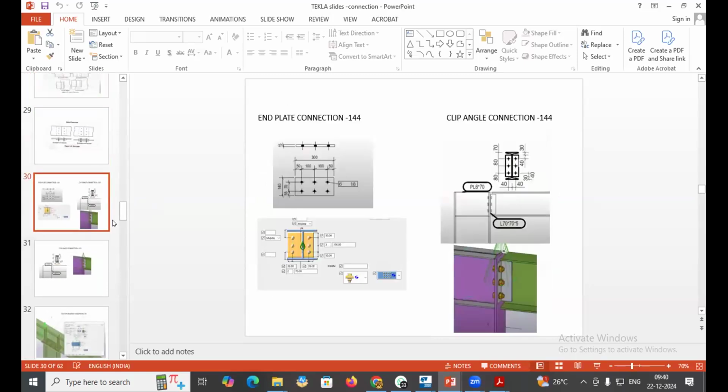And there are some sample connections here, and I have highlighted the values also here, and how we are going to work, because this is the 2D set of drawing. Based on the 2D drawing you have to work in 3D, how to create the column, beam and the connection. And the reverse process is, after finishing this connection you have to give numbering, and after giving numbering you will highlight the names which we provided while creating the beam and column. That will be highlighted after extracting the drawing from the 3D model. You will get this kind of input. So both sets of applications you have to work on as an assignment.